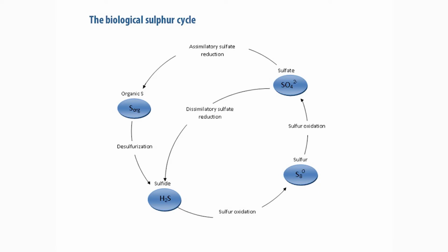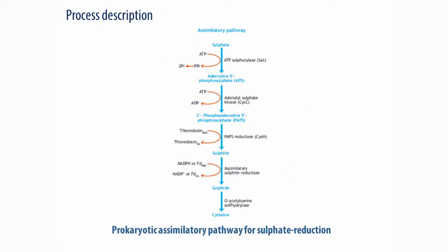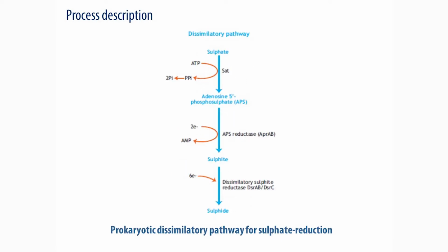However, during anaerobic wastewater treatment, sulphate can be reduced back to sulphide by sulphate-reducing bacteria, also known as SRB. Assimilatory or dissimilatory sulphate reduction are the most important anaerobic processes that affect the conversions of sulphate. The initial step of biological sulphate reduction involves the transfer of exogenous sulphate through the bacterial cell membrane into the cell. Of both processes, the most important is the dissimilatory pathway.